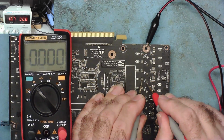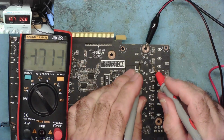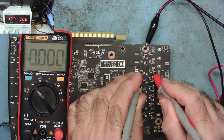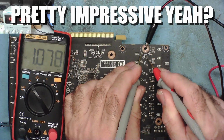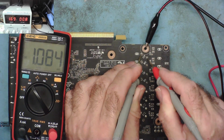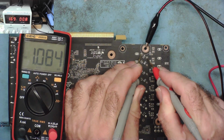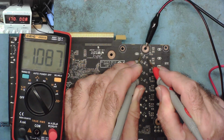So that one's reading 0. This one's reading 0. This one is reading 0. Does this one show a voltage drop? Yes, it does. So we know the current is flowing through this coil. So this method has determined which coil, which phase, has the short circuit high side MOSFET.